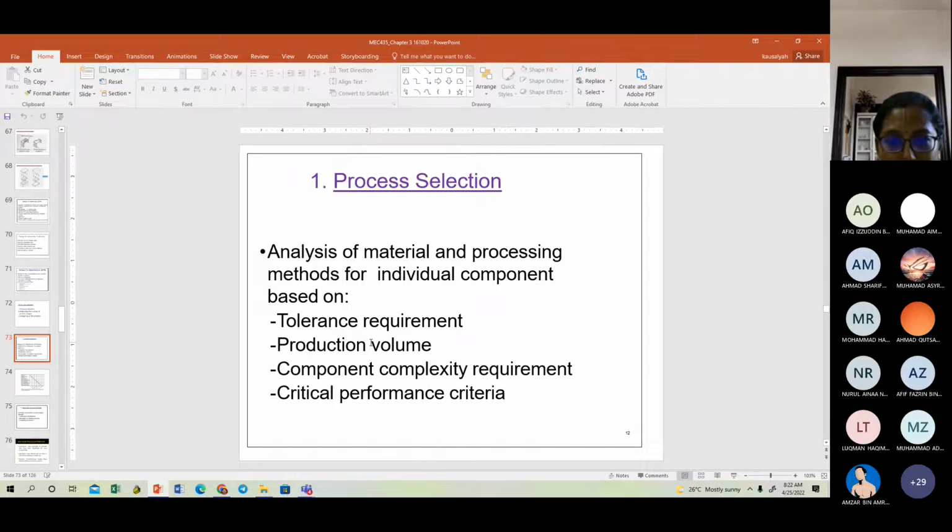Casting is a process which does not generate large volumes. It's more for smaller volumes. Injection molding can be chosen for large volumes, and you can also have very complex, detailed design in injection molding. We can't have that in casting. We can have fine, detailed grooving in machining, for instance. So based on the product that we are designing, we should be choosing the machining criteria.